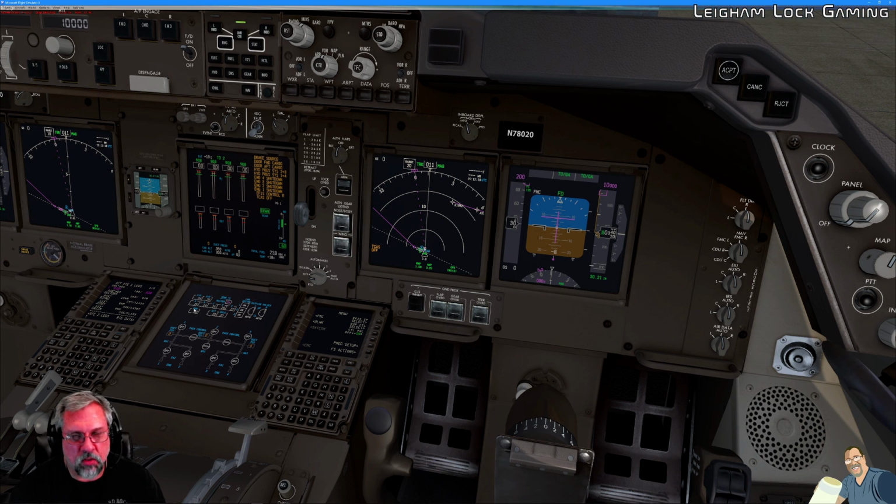First officer, at this point, even though we are not taxiing or taking off yet, we can go ahead and put the auto brakes into the rejected takeoff position, so we'll knock that out now. That is a checklist item.